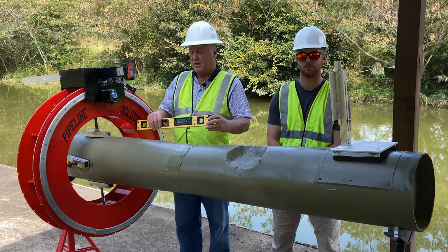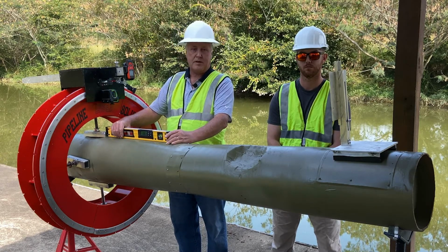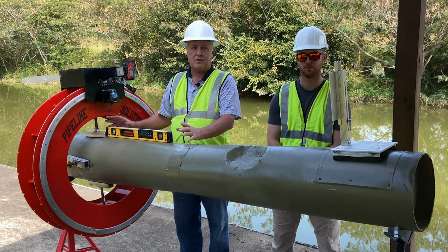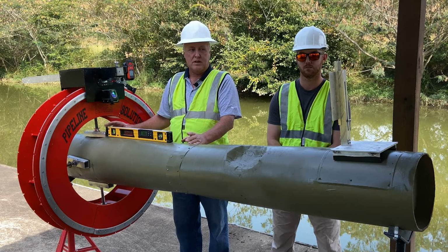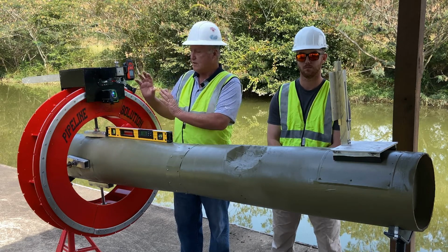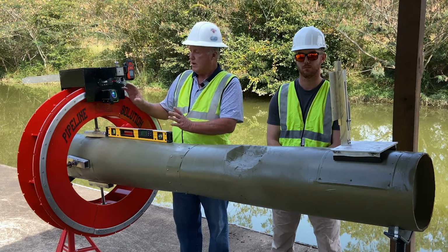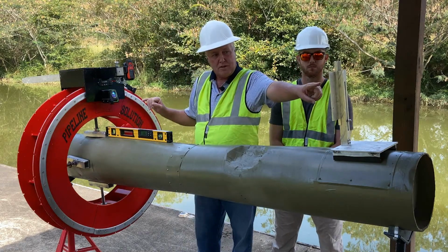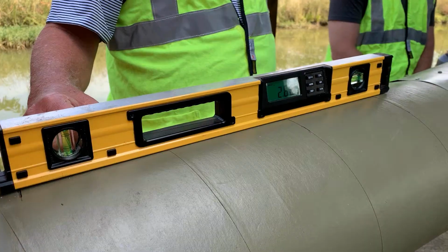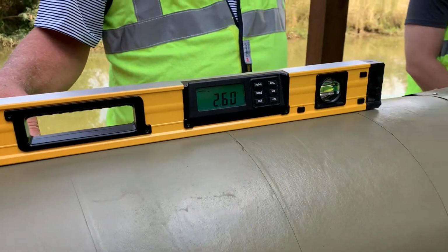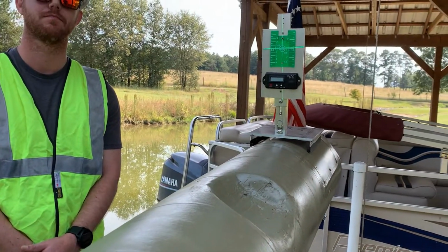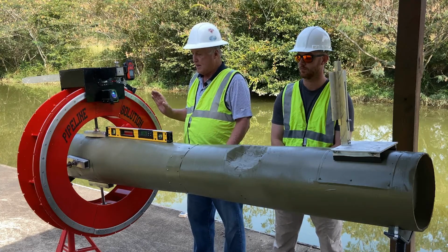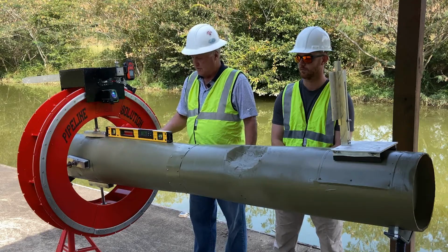So the first thing we like to do is, and all this equipment comes with your unit, you've got a level here and it's approximately 2.6% out of level. And so once we find that out, we can start setting the equipment up, and we have a measuring device here that points out to a target. And once that gets centered on that target, then we are parallel and we're centered to the center of the pipe. So all our measurements all the way around will be exactly the same from here, from the laser to the center of the pipe.